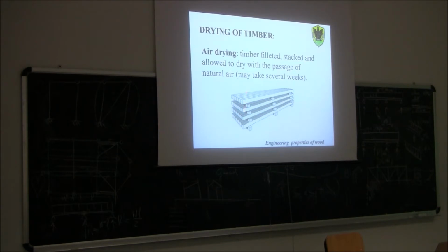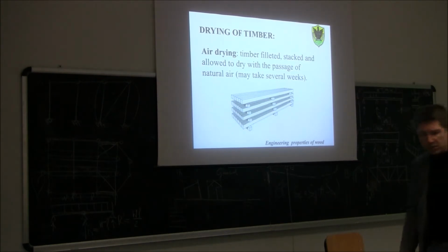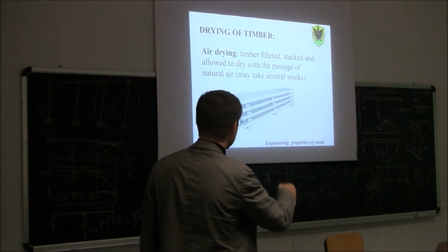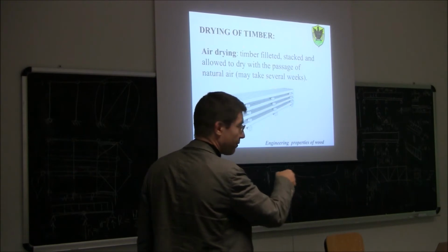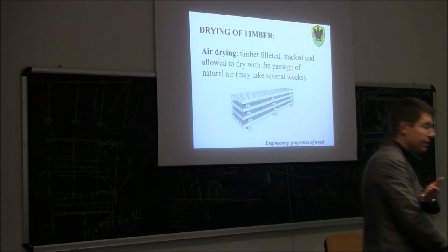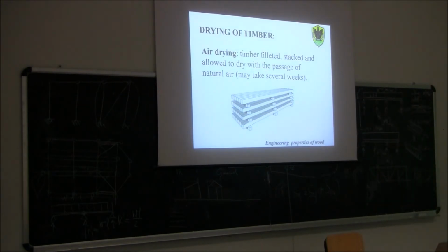And then you need to fillet the timber, stack it, and allow it to dry with the passage of natural air. You might have seen this when you go in the countryside, perhaps not so much here, but more in the Alpine region. Sometimes we have these kinds of piles of wood. Of course, what is missing here is a roof, as you can imagine. You can't have this without a roof. Because if you leave it outside on a day like this, you have rain, and you lose immediately. The water can immediately increase the moisture content again. So you must have a roof above.